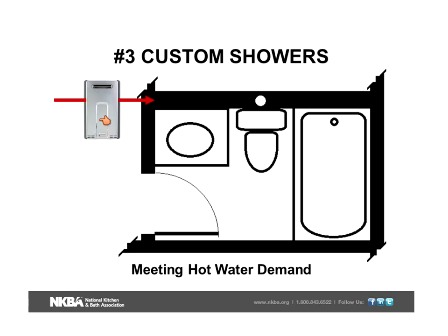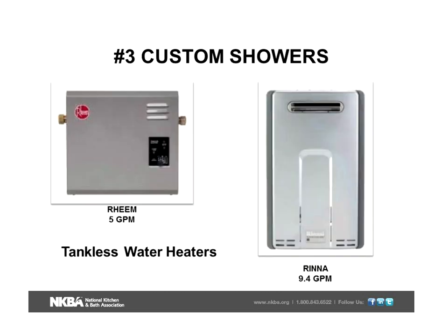So one that would be rated at 3 to 4, we'd probably be okay. But let's go back to changing this to body sprays and other water delivery fittings that we'd have in this home. This on-demand may simply not work for us. And again, they are rated in gallons per minute. We can see this one is 5, but keep in mind, 2 shower heads, and you have this one at its limit. 2 people taking a shower at the same time, you have it at its limit.